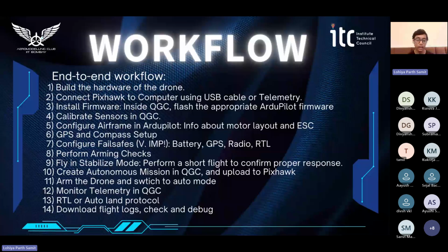And then at the end of the mission, it can return to launch or it can auto land depending on the protocol that you have set up. Then at the end, when it has landed and de-armed itself, then we can download the flight logs, check and debug for any further updates.